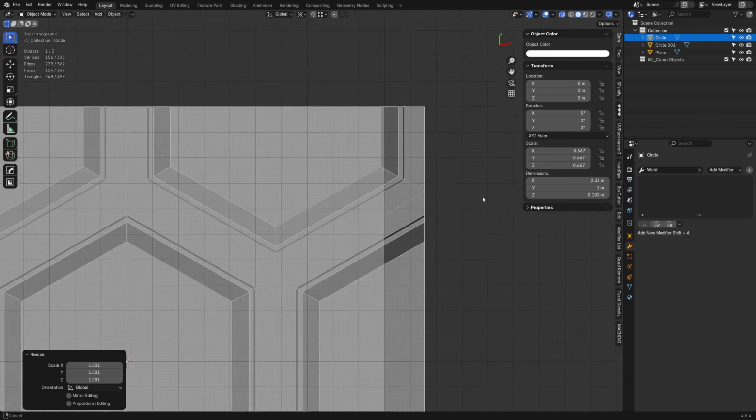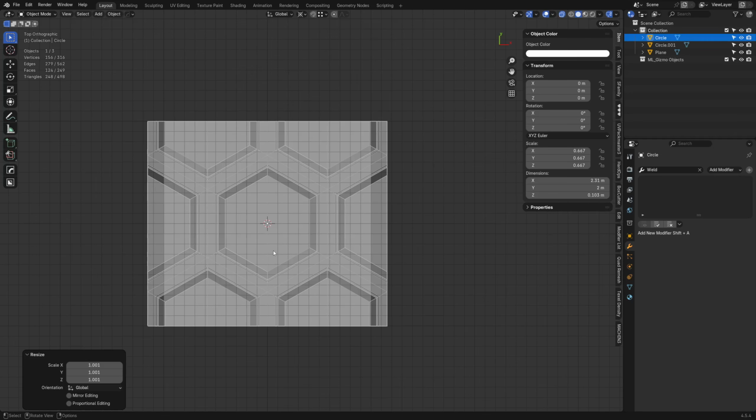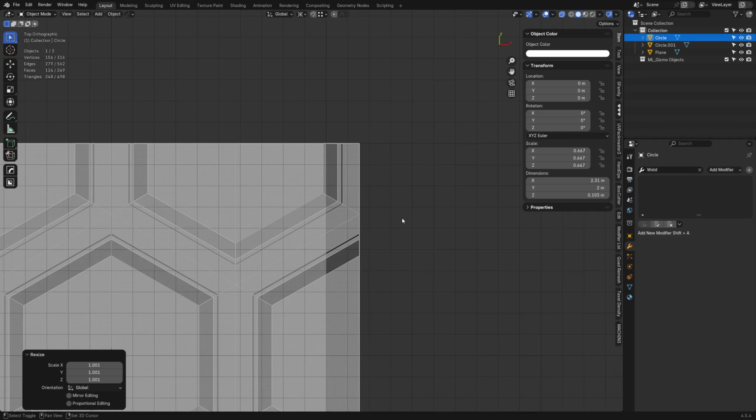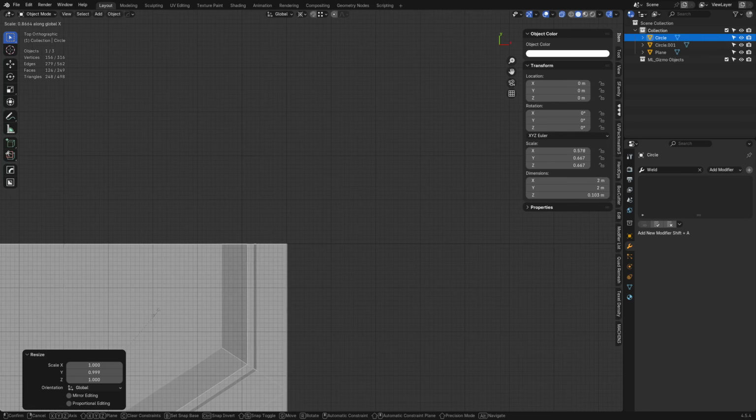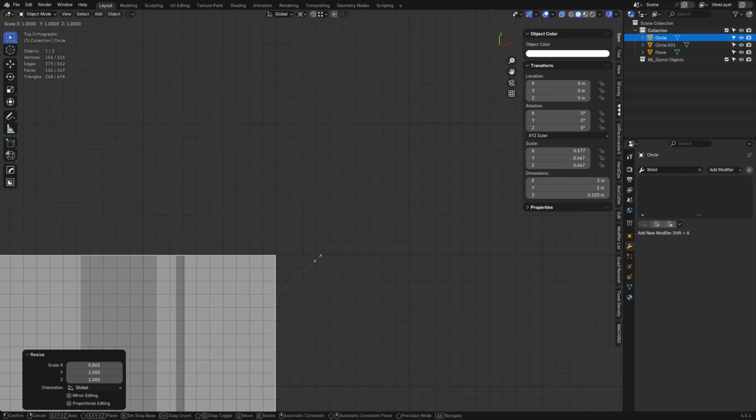There's an origin point on this. Oh, the origin's okay. If the origin point was somewhere else, you would use the 3D cursor. Right now, we could probably use the origin. So we scale on Y, SY, hold Shift, SX, hold Shift. Same kind of idea. We just line things up real quick, our little reference, and this should work out pretty well.